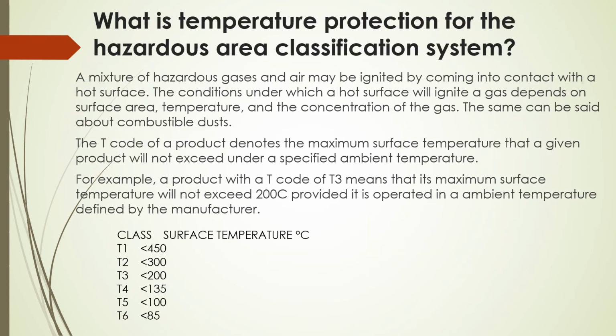What is the temperature protection for hazardous area classification system? A mixture of hazardous gases and air may be ignited by coming into contact with a hot surface. The condition under which a hot surface will ignite a gas depends on the surface area, temperature, and the concentration of the gas. The same can be said about combustible dust.